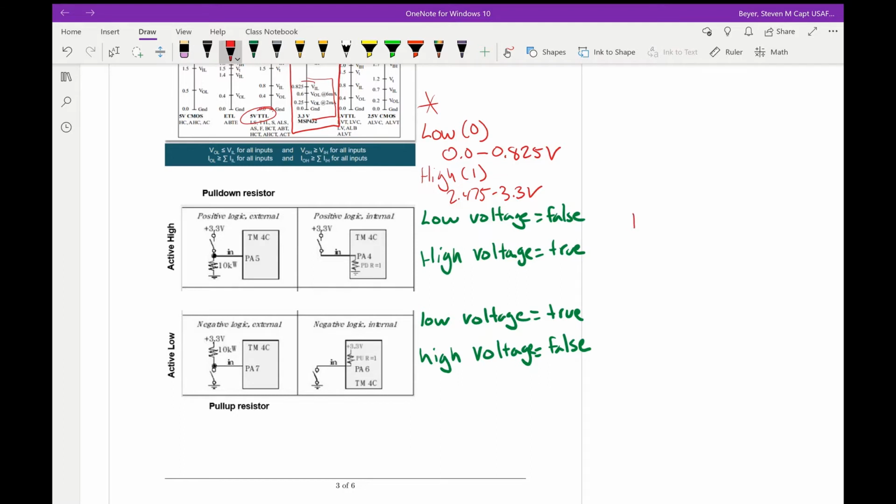We can do something along the lines of, if read the bump sensors, bump equals P4 in, and then we can do something along the lines of, if bump, and then if any of those, so if they're all 0, right, so no bump sensors have been hit, then as soon as one of the bump sensors is hit, it doesn't matter which one, the if statement, as long as any of these or multiple of them are 1, then this whole statement will become true.